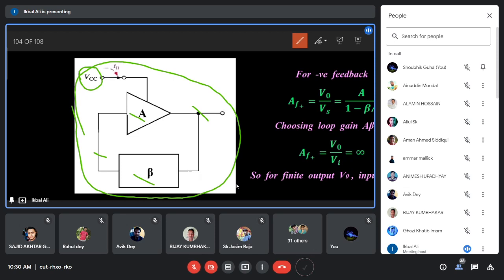It does not require any batteries or any energy supply, but the amplifier does require a battery DC supply. Why? Because the input of the amplifier is a small AC signal and the output of the amplifier is a large AC signal. So the amplifier has to be fed some DC energy such that it can convert a part of that DC energy to AC, and that is why the output is boosting. We have discussed this, calculating efficiencies in the power amplifier. We have understood this.